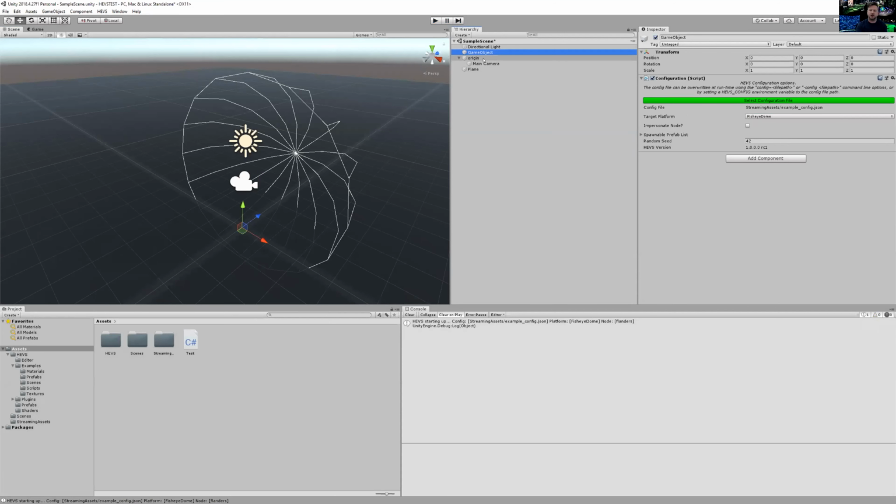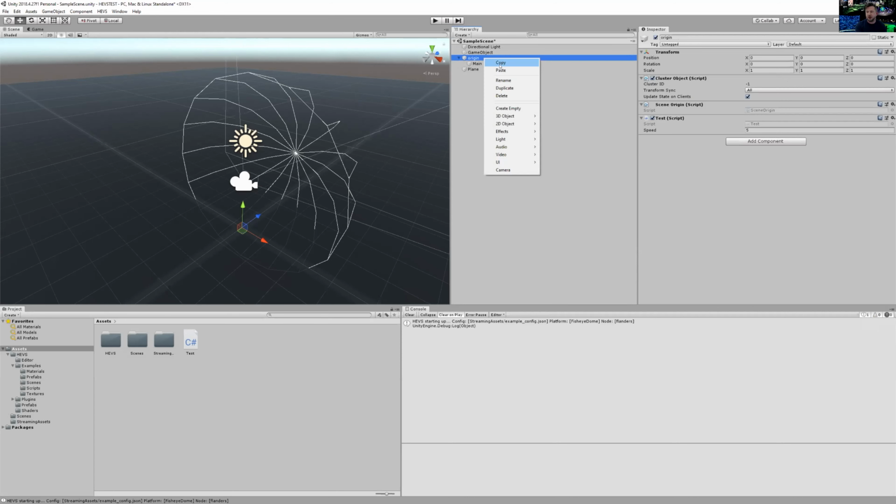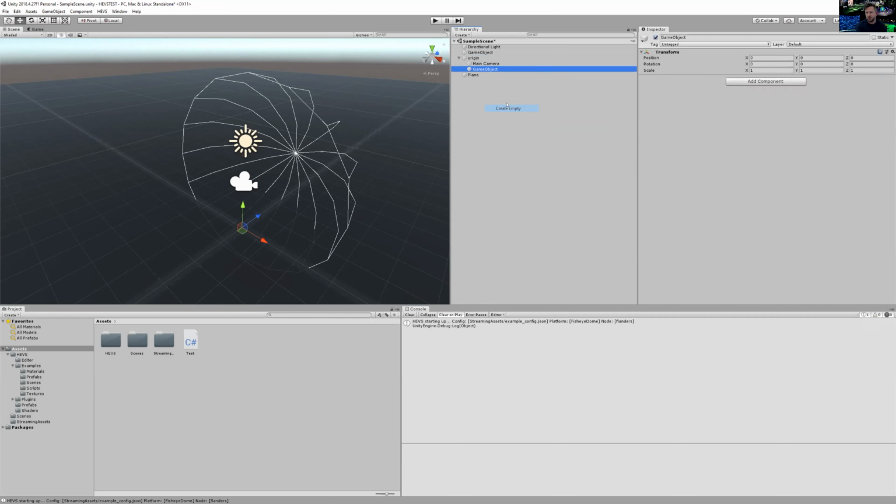One other quick little thing to do is you would typically want some sort of tracker, say tracking just one thing in the cylinder, or we can broadcast the XR trackers over VRPN. We have a tiny little script that we can give people that'll do that for you. But if you wanted to track something, it's quite easy. I'm just going to create an object that I'll call, say, wand.